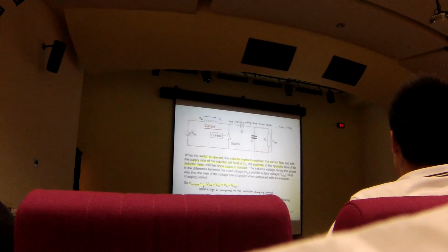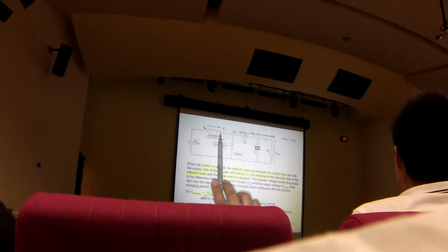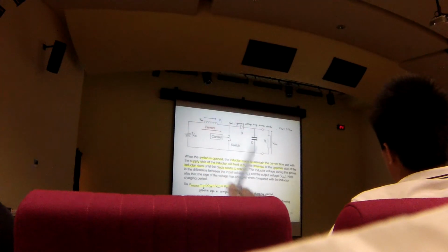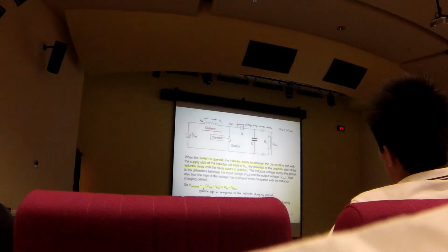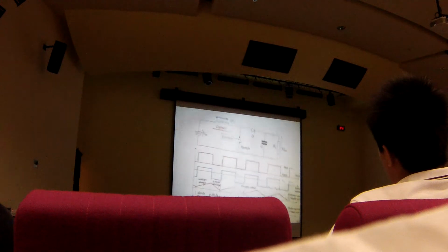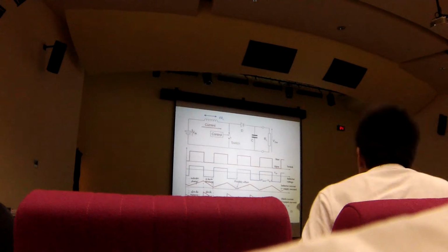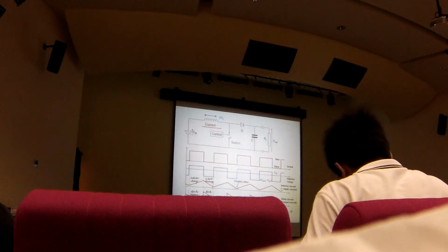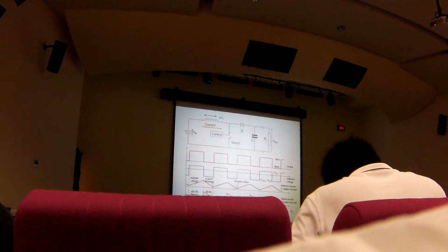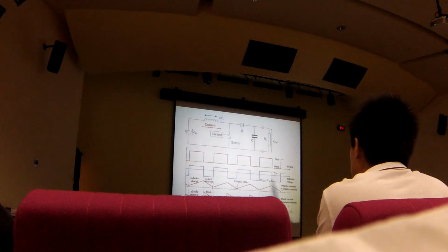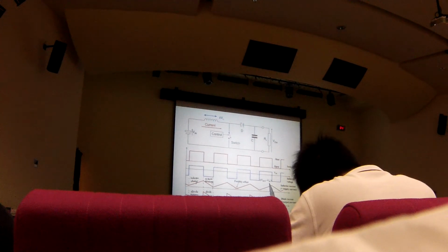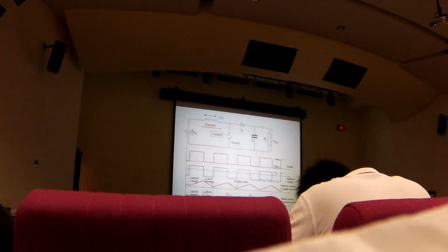Okay, so in this case, the charged inductor will slowly discharge and energy in this magnetic field will fall, which is illustrated by this waveform. Alright? Okay, so this is opening and closing of the switch, and the inductor voltage will fluctuate from V-in to minus (V-out minus V-in), and the inductor current is like this.